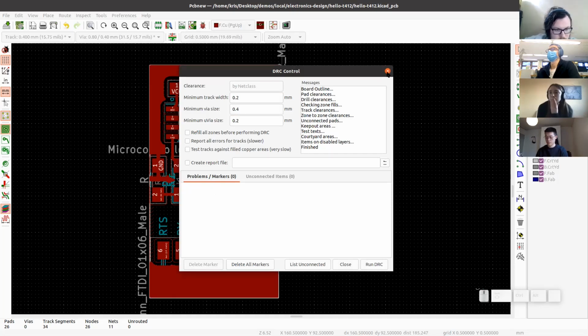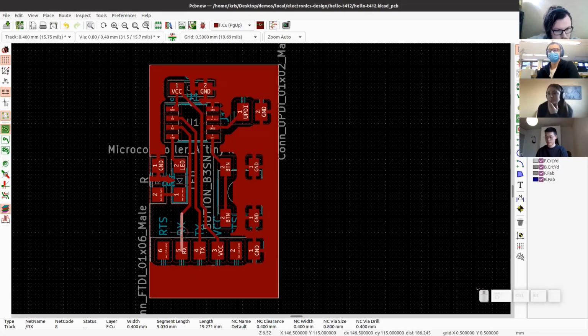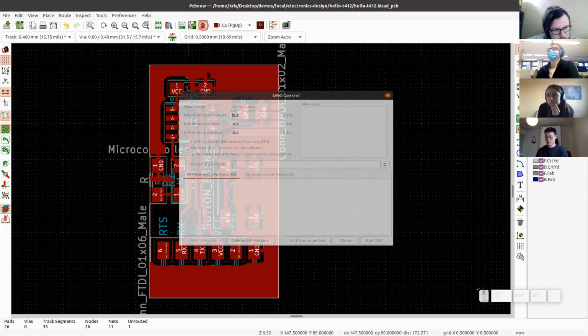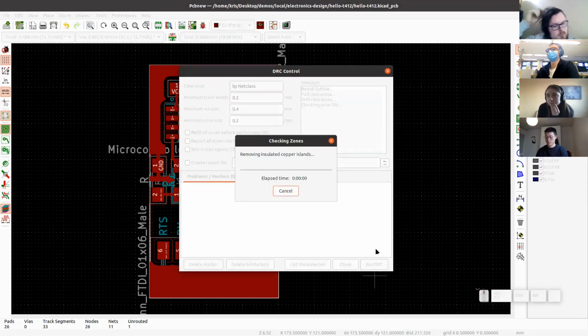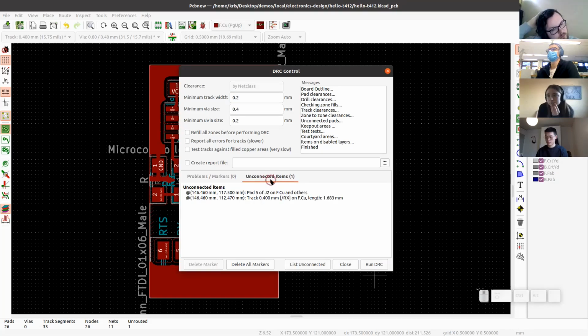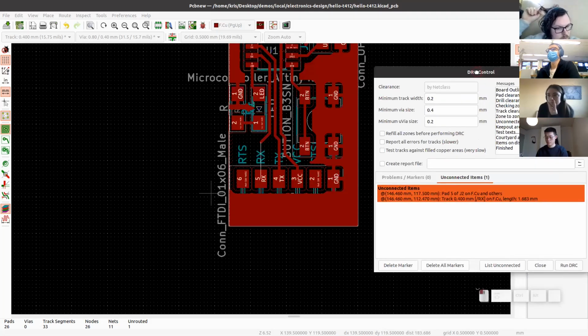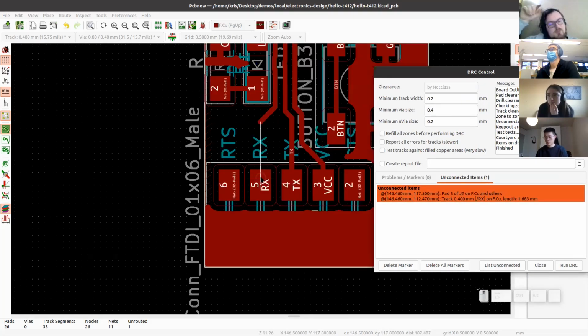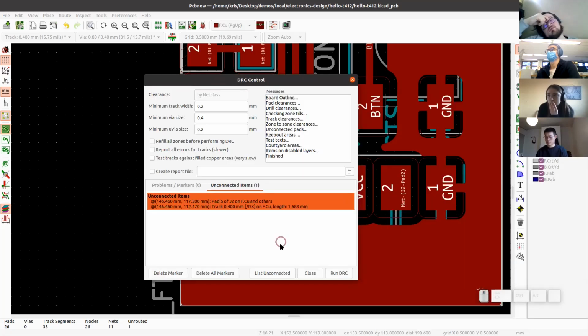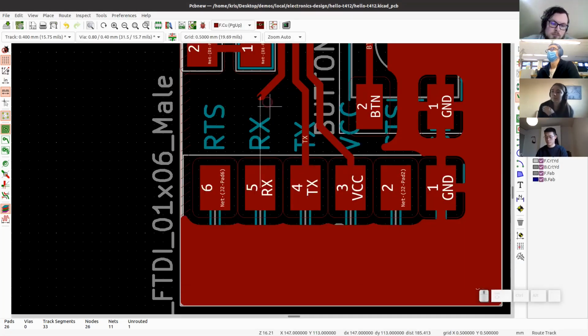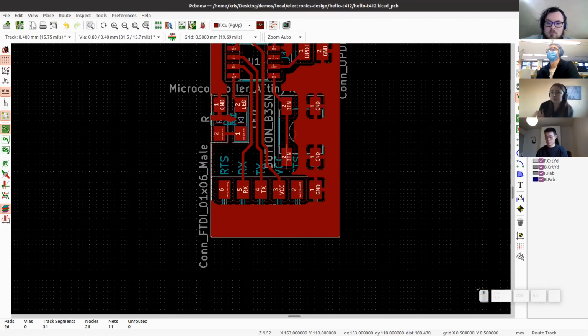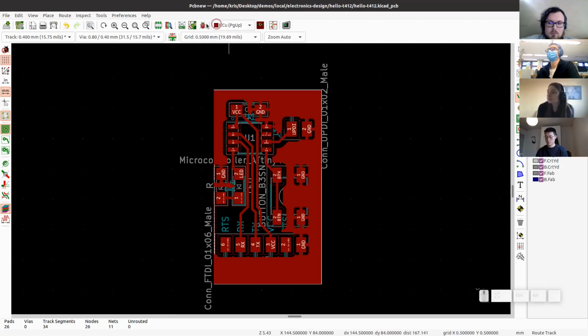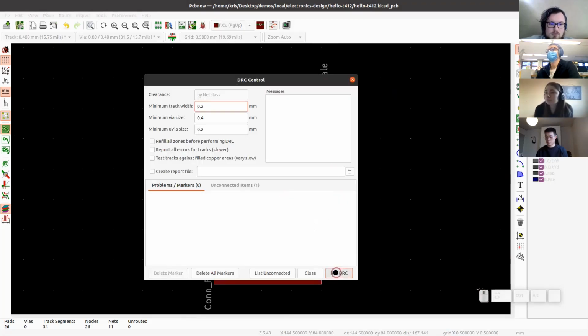And this is not good for learning because there are no errors. So let's leave something disconnected like this, for example, and run the debug thing. And it's going to show us one unconnected item. So unconnected items here. It's going to center that in the page. This is our unconnected item. Close and connect it again, like so. Just to double check. DRC. So 0.